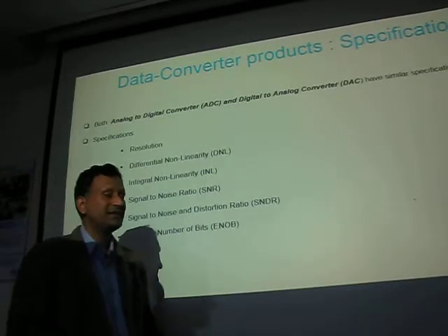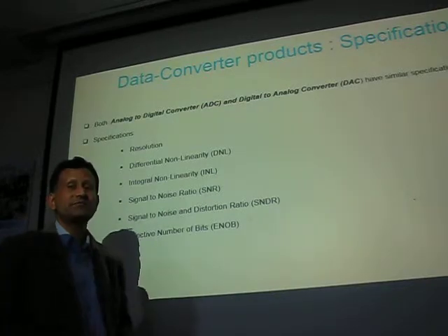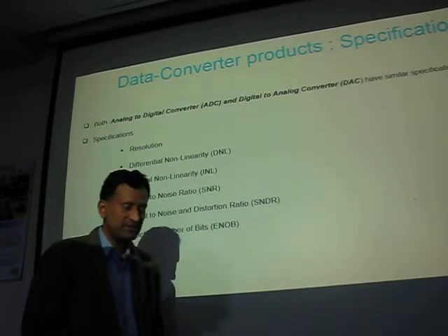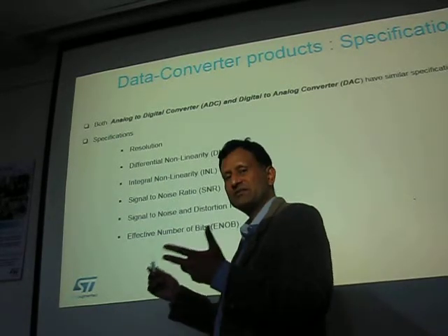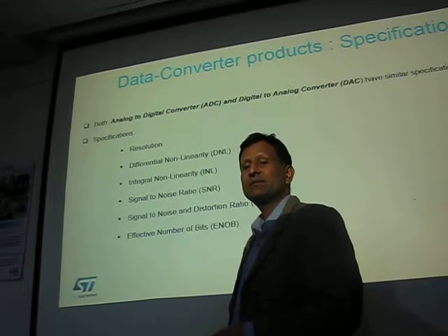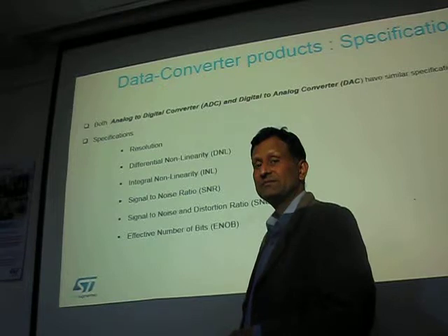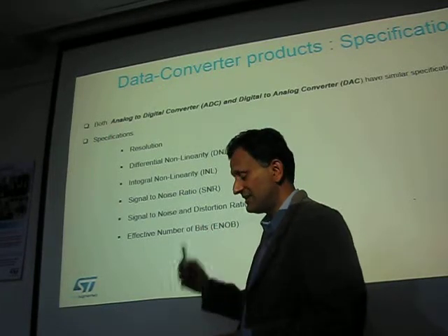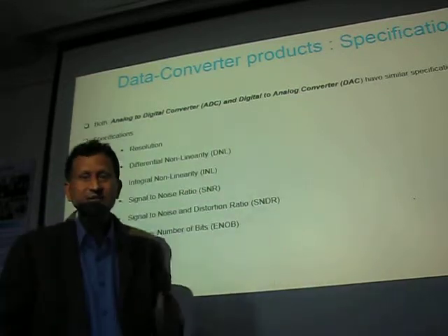How good our data converters are is decided by their specifications. There are some major specifications like resolution, differential nonlinearity DNL, integral nonlinearity INL, signal to noise ratio SNR, signal to noise and distortion ratio SNDR, and effective number of bits ENOB. Let's see them one by one.